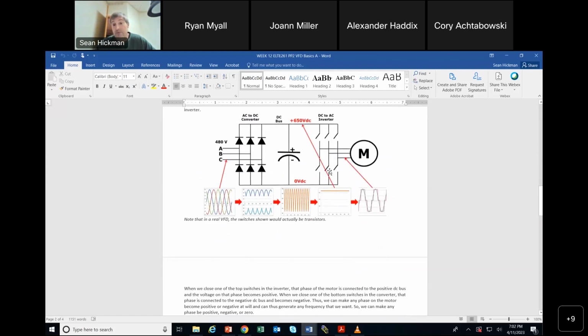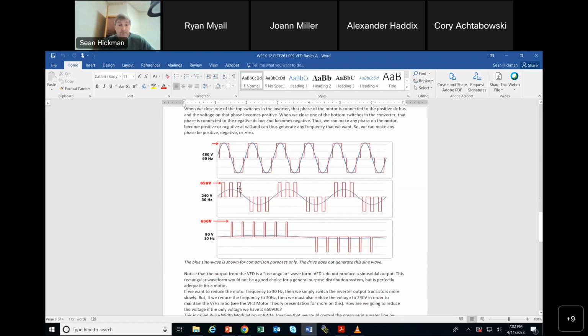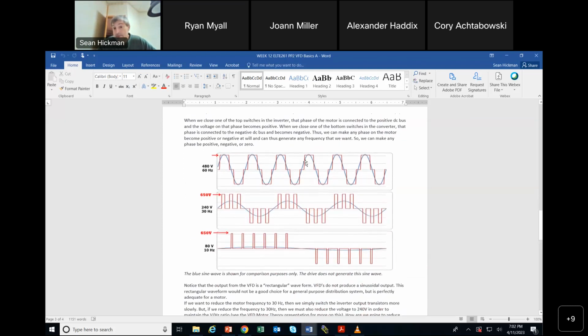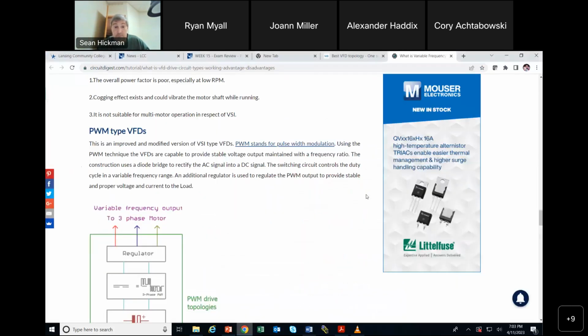And then, like I said, you move these switching mechanisms. They're showing the switches here, but these are solid state transistors moving rapidly, and you would get AC voltage, or something that looks like this. All right. And so how long you keep those closed allows you to simulate your AC curve here. It's a square curve. It's called square because it's not smooth. You could get a pulse width modulation that we talked about just a minute ago. That was our pulse width modulation.